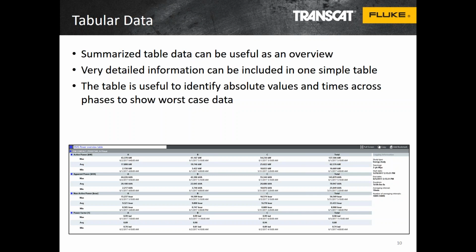And then we also can see what the average is. On the averages, we see, for example, that there is a difference. We go from 17 to 25 kilowatts in this case. So there are some single phase loads on some of the phases which are drawing more. It just tells us that probably whoever installed the equipment in the first place decided to site the equipment on phase C rather than phase A.